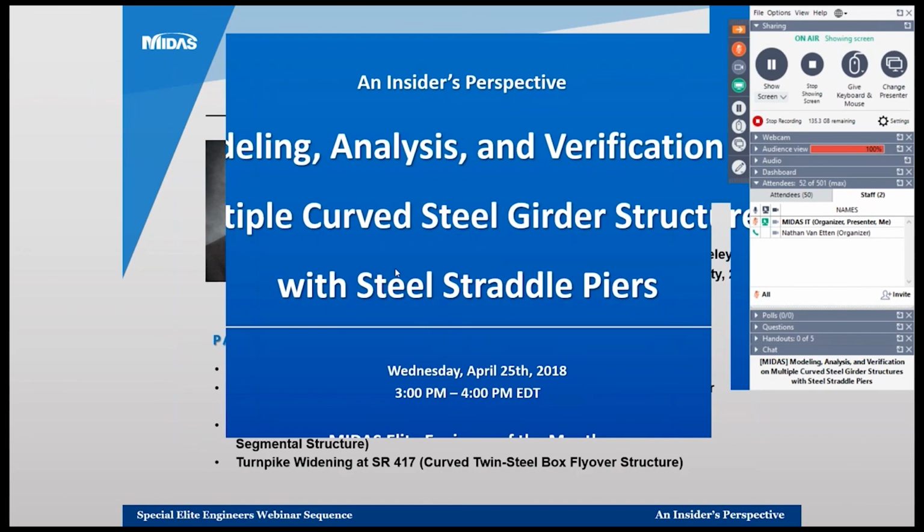Something would go from a 250 kip per inch spring condition to a 235 kip per inch spring condition between dead load, live load, and the point load applied. However, they were not noticeable enough to cause a large differential in analysis. So what we did was apply the average spring effect between all of these conditions, and we were very happy with the results.